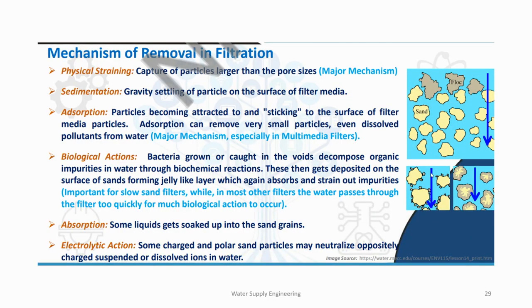So the mechanisms of removal in filtration are of different kinds, namely physical straining, sedimentation, adsorption, biological action, absorption, electrolytic action. The first one is physical straining. Physical straining is the major mechanism. Here, particles larger than the pore size of the filter media will be captured.